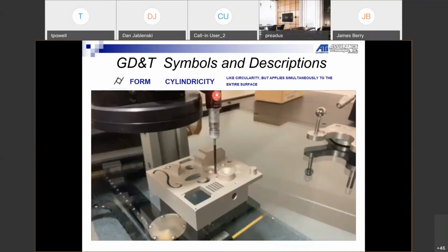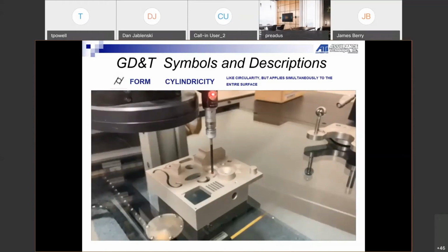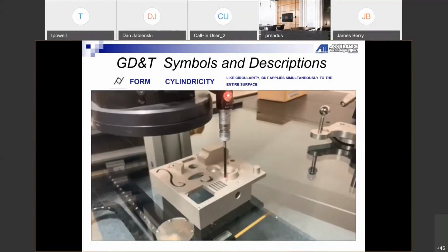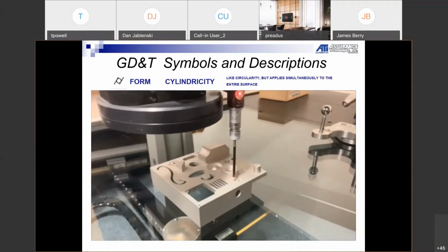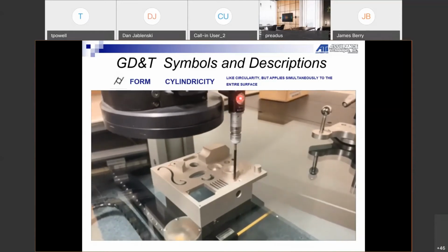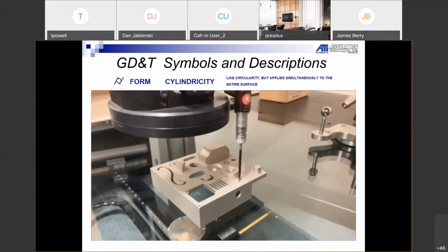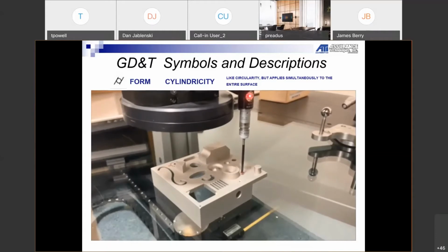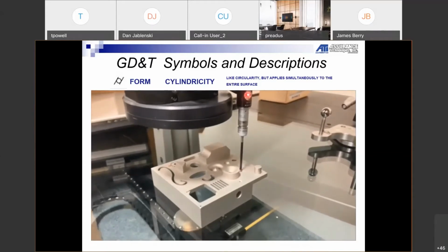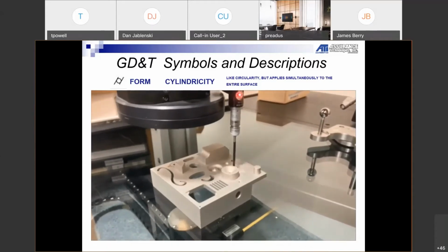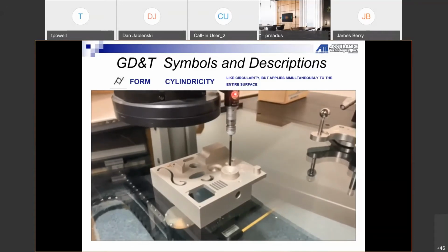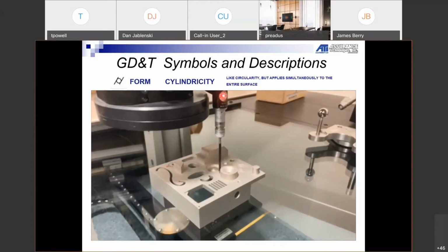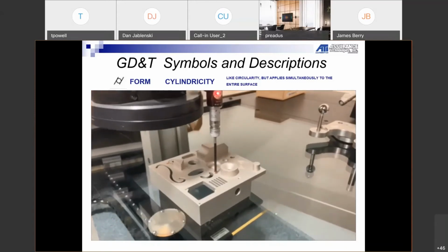Here I was measuring cylindricity. So I bring the touch probe over, I took 1 point on there, and I was able to rotate every, I believe it was 20 degrees. I do a lot of points around the cylinder when I rotate, because you got to be careful on the outside diameter of it. Without move through points, it's gonna crash into that cylinder. So you could even do every 10 degrees and take 36 points around that diameter, and it'll safely move around